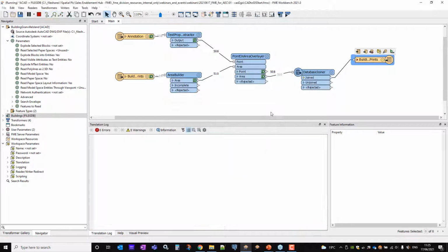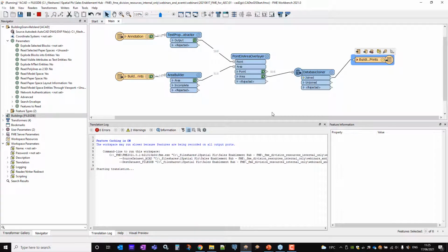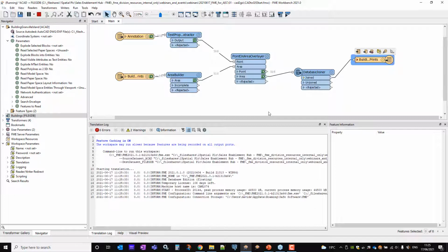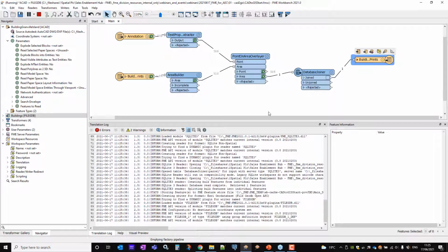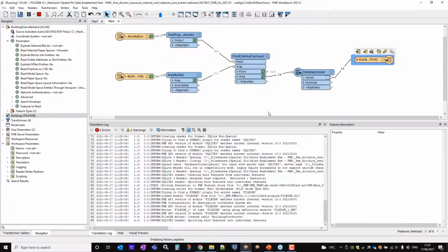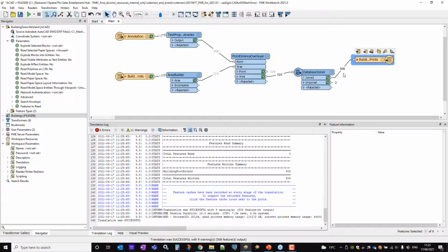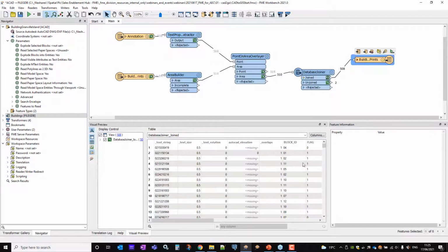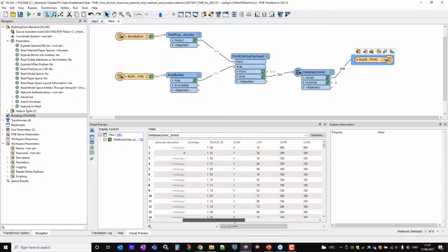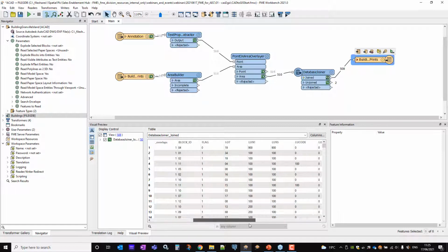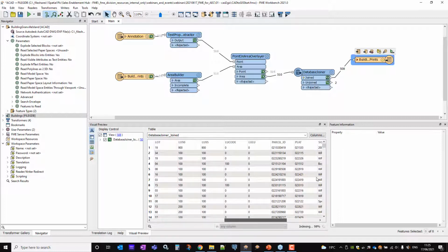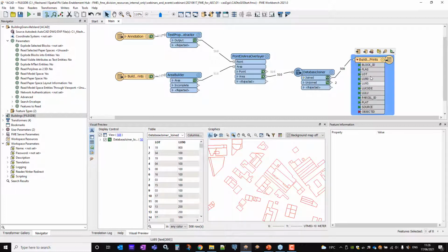So if I run this process, it will go out using the primary key, which is the ID that I fetched from my label and joined onto the polygon. I can then query the database where the IDs match and bring back some additional information to my resulting features. And you can see here that now I've got things like a flag, a lot number, a LU code, a block ID, all the extra details that are wanted in order to populate my target schema.